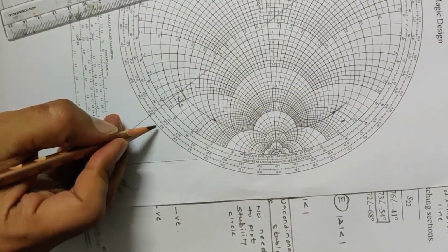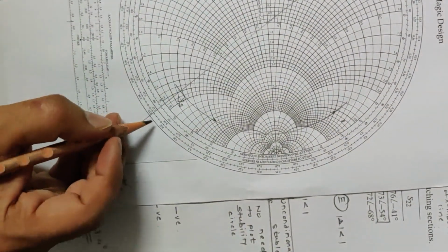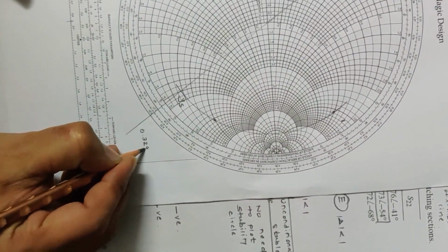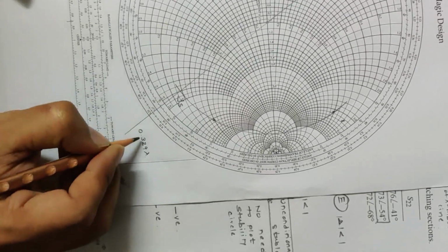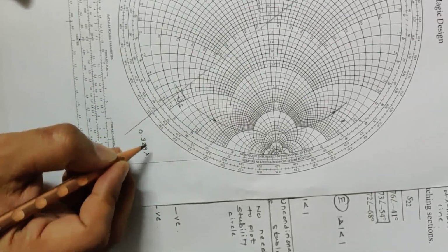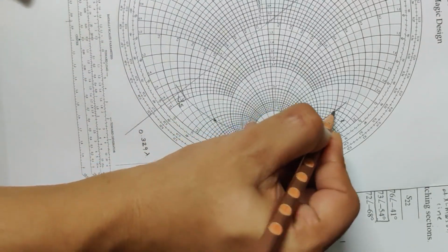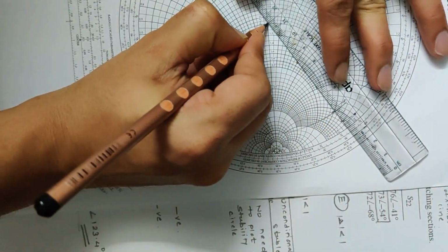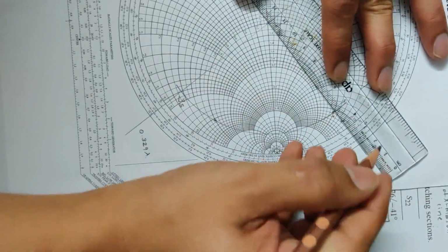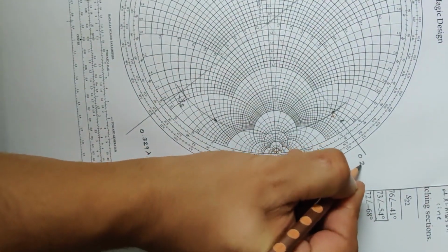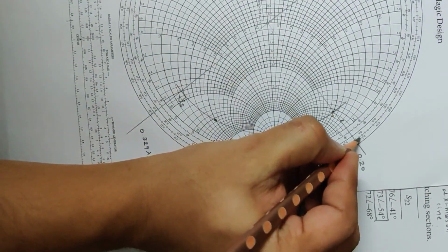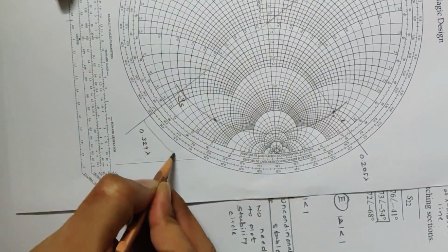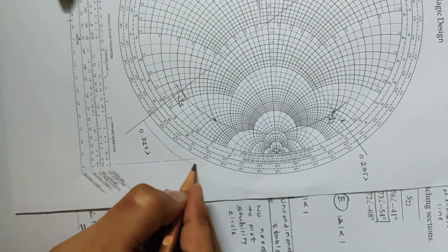So I will read this wavelength scale over here using the outer wavelength scale. So it is around 0.329 lambda. You may get some different value, but near about this one you will get. Now this is the point of intersection of the constant VSWR circle and the unity circle. So extend this thing on the wavelength scale, and this turns out to be 0.20245. So one has to travel the distance from YS to Y1 over here